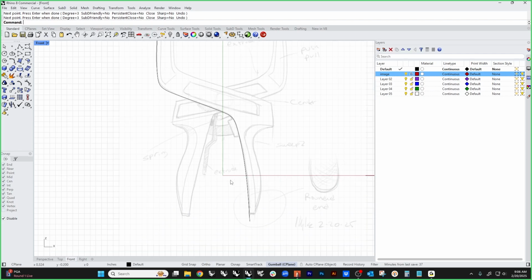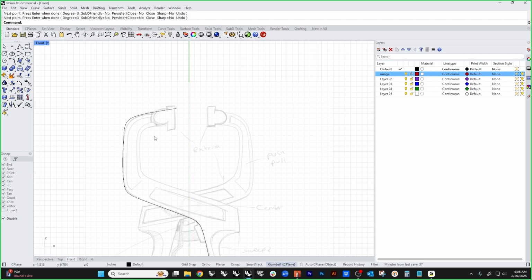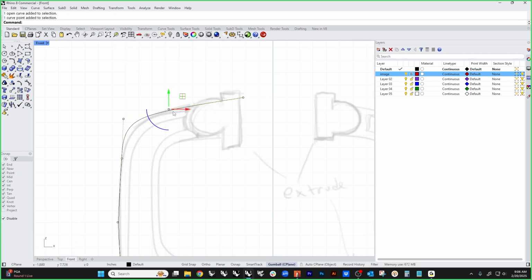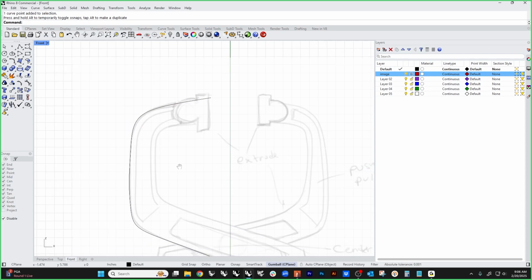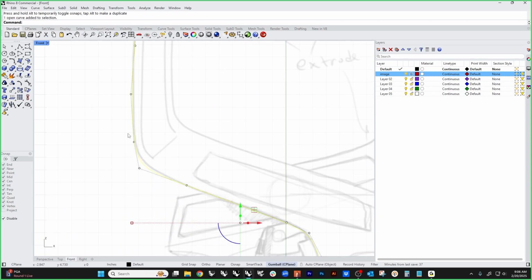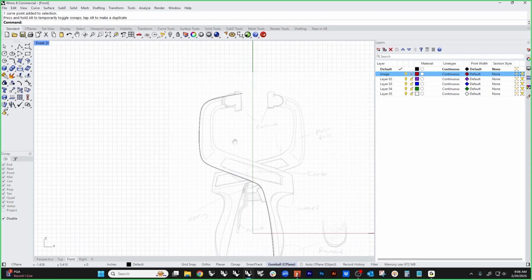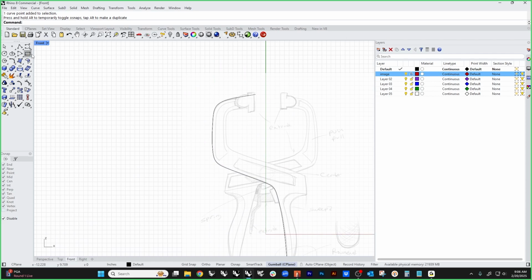bookmarking it for later, and you're going to watch that and learn everything there is to know about making nice, simple corners in NURBS instead of machine gunning points into a corner and making a big, giant mess. And if you're not, then we're going to do a 2-second talk about rule of 3. Rule of 3 is 3 points to make a corner. Okay? That's as simple as it gets.